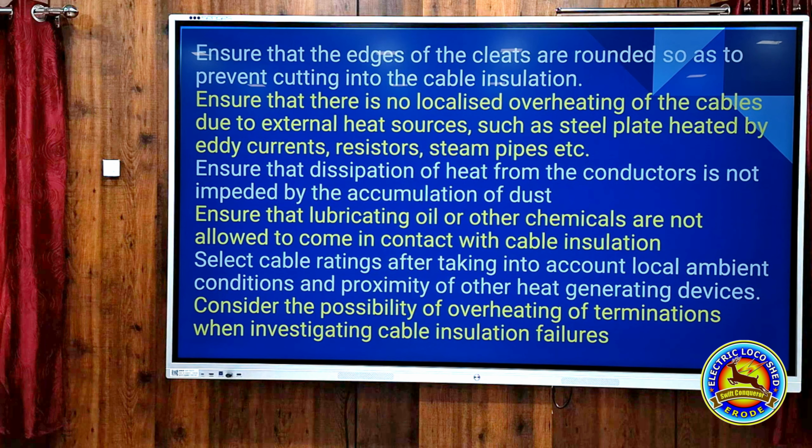Ensure that the edges of the cleats are rounded so as to prevent cutting into the cable insulation. That is, all the cables in the cable trench or wherever fitted should have proper cleats, and the cleat edges should be curved and should not be sharp. That is, it should not cause any damage to the insulation of the cable.